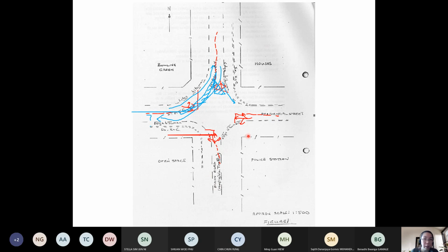Okay, so these two you are traveling only at 60. So it is not equal. The road classification here is not equal between the state highway and these two, residential and main road. All right, so if you put a roundabout here, it means that everybody's priority is the same. There's no priority. But in the question, what we want is to give priority to state highway users. All right, so I hope that explains to you why we are not using a roundabout for this question.